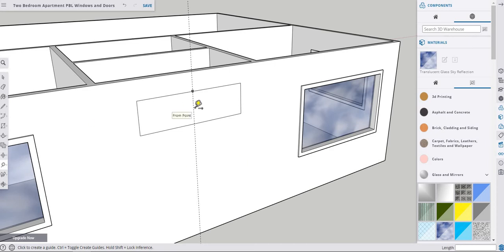Okay, now from this line, we're going to go 3 inches to the right. No, excuse me, 1.5 inches. Actually, we're going to wait on that. Next thing we're going to do, tap spacebar. We're going to use the offset tool, that's F. Grab from here, drag out 3 inches, enter. Okay, so that's going to give us our lip on that.